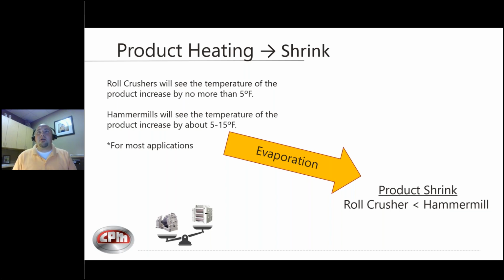Looking at a couple questions here, I see someone just asked on loss in moisture. For the most part, and just to make sure we cover it, as moisture does decrease within the product, we do see an increase in fines as well, just because drier material grinds easier and we see more fines.